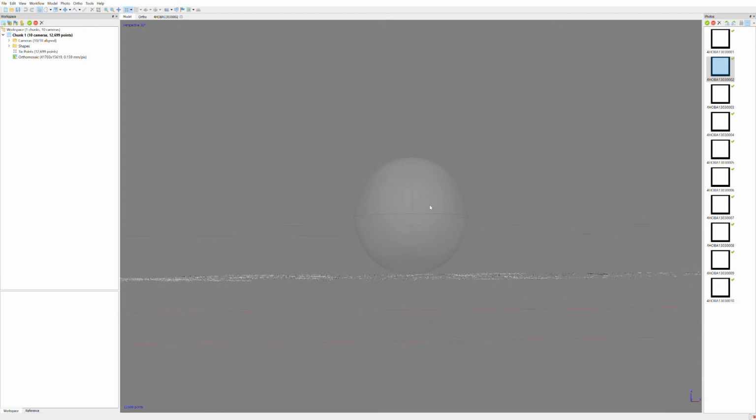If you have points that are obviously causing issues, or you see different levels of your planes, then you might have to troubleshoot that. And if it's just an entire mess, you might ask someone for help, or maybe just scrap it. Maybe the image collection was so poor that it's just not possible to get a good product out of it. I'm going to click on this camera to show cameras, just to show this is where the program figured out the cameras were and the way that they're facing, so you can see they're flying along in a single line taking pictures.